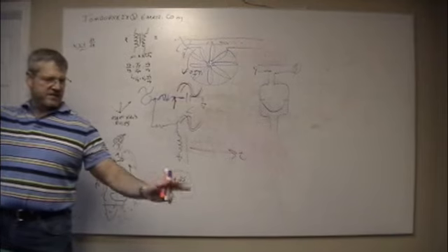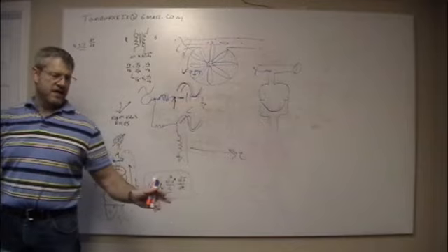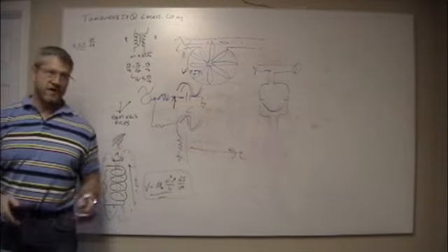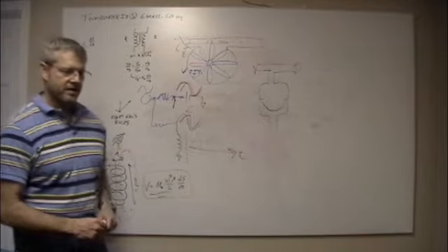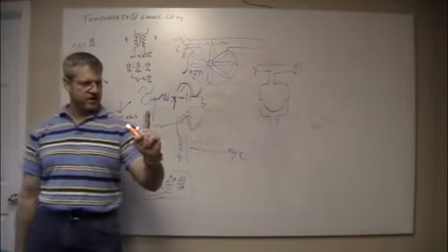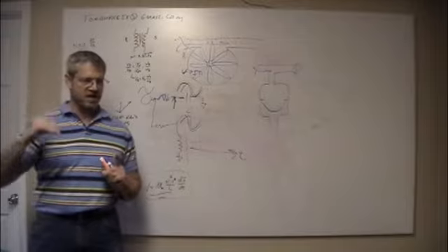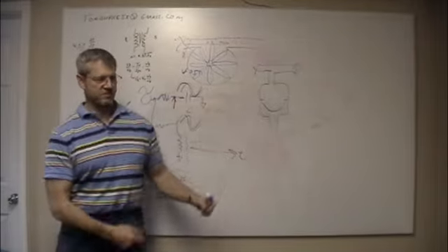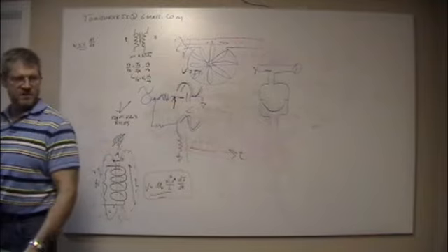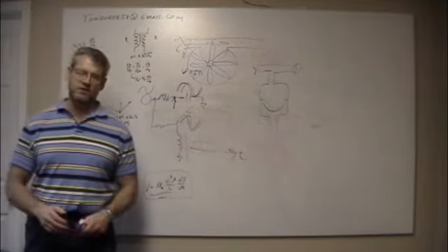And you talk about a phase angle and a power factor. A power factor is the cosine of the phase angle, if I remember right. So if your power factor is 1, that means you're perfectly in line, and you're using the current as the voltage is being supplied, and not using it as it's being taken away, or giving it up as it's being taken away.